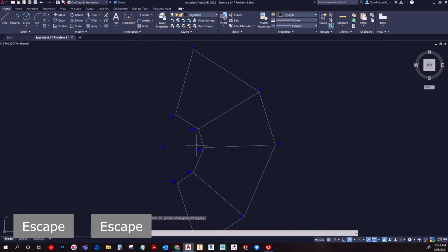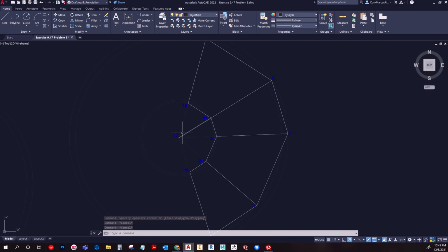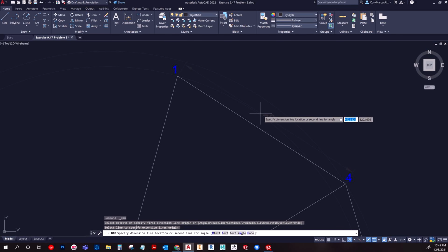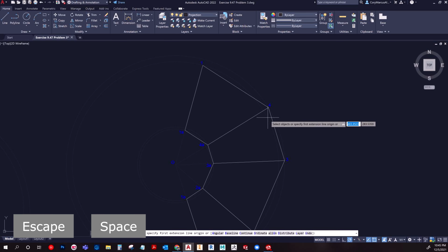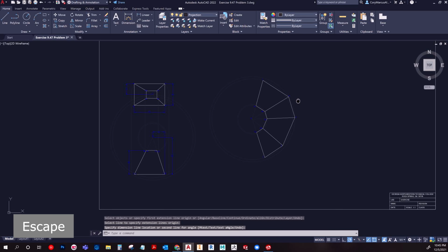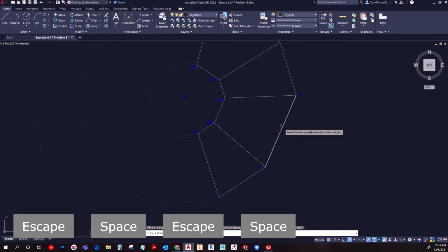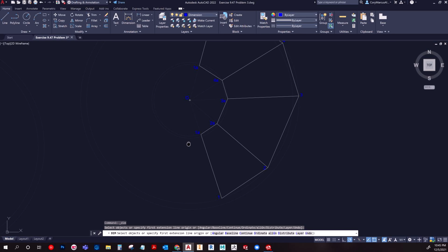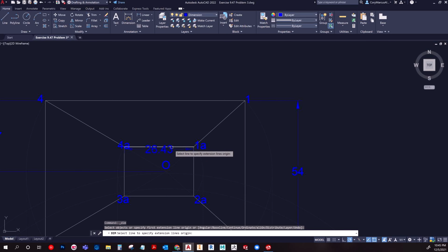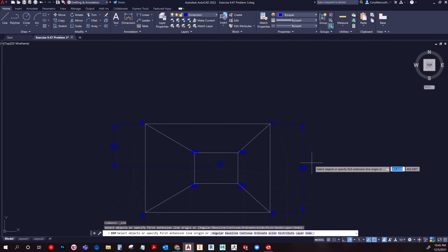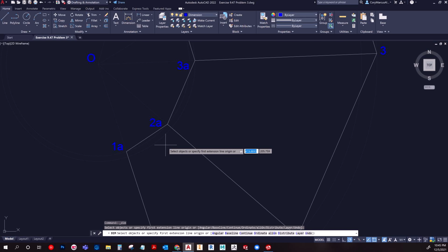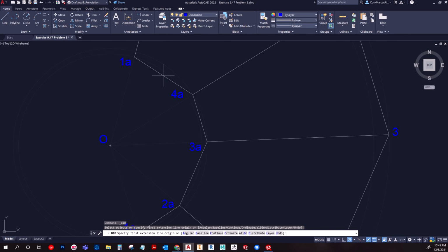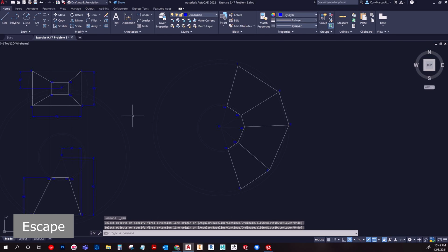And there we go. So now we have all of the side faces, and you can confirm these values are correct to an extent. Obviously the width here should be 76. It is. This should be 54, and obviously the same across it all. Now we can see a little better, but the same applies up here. If I were to dimension the top, we have 26.43 and 18.78. So 18.78, 26.43, and the same around. That tells us we're on the right track.